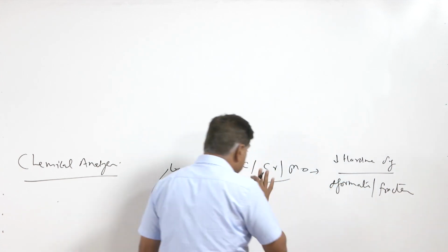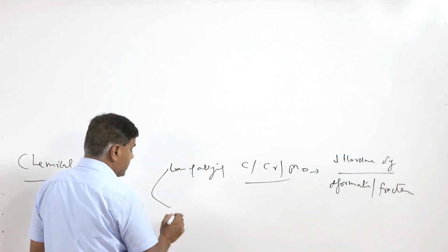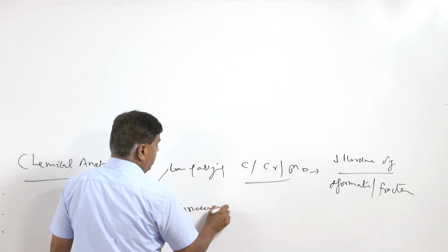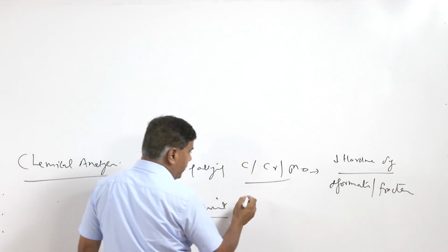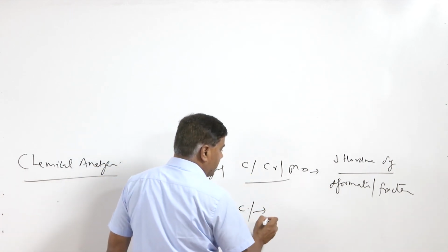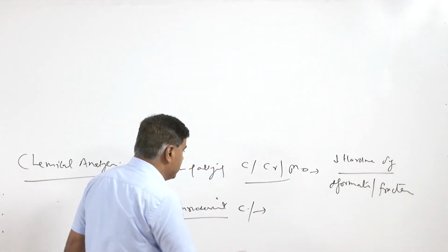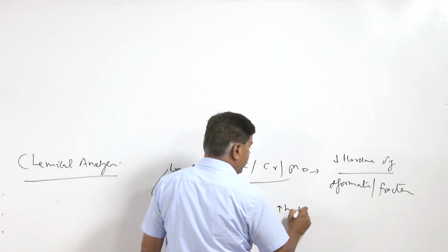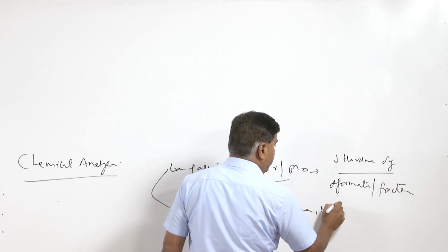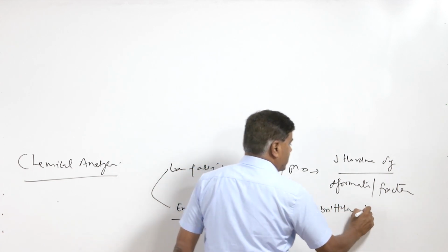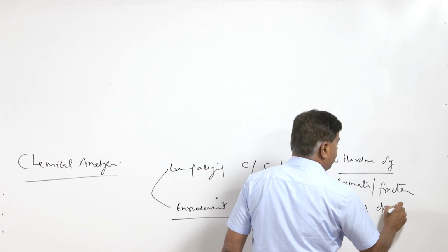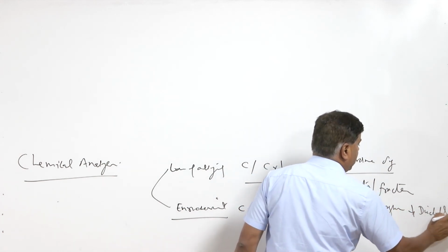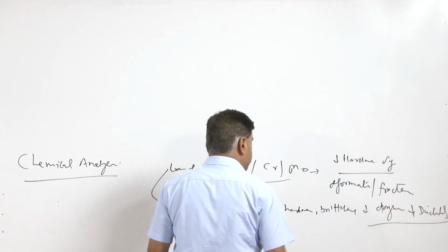So we need to really establish whether any losses or enrichment of the alloying elements have taken place. If addition of carbon is taking place, say during carburization, then it will lead to an increase in hardness, an increase in brittleness, a reduction in toughness, and a reduction in ductility.